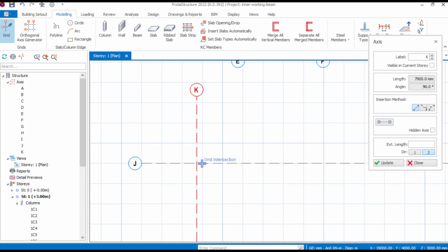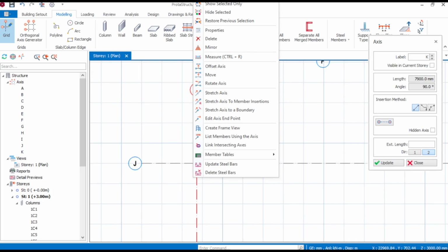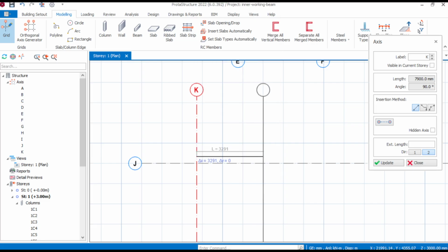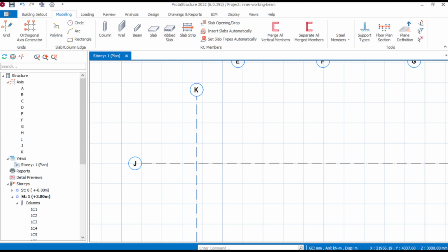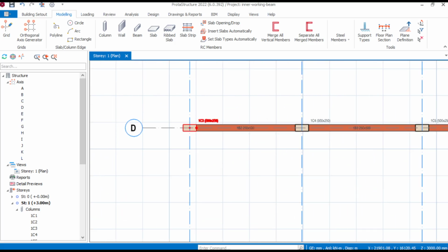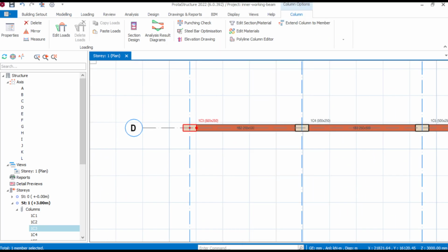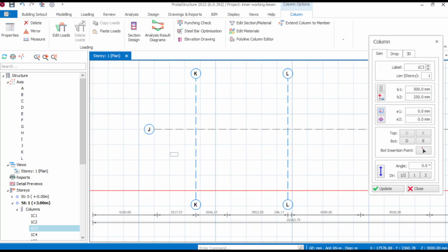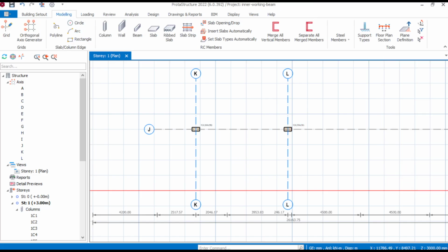Same thing. So from here, let's offset 6 meters. So offset, right click offset, then you have shift F2. You have 6,000 millimeter. Very good. This is very, very good. So let's get our support. So let's go to properties. Let's place our properties. Then let's go to beam.